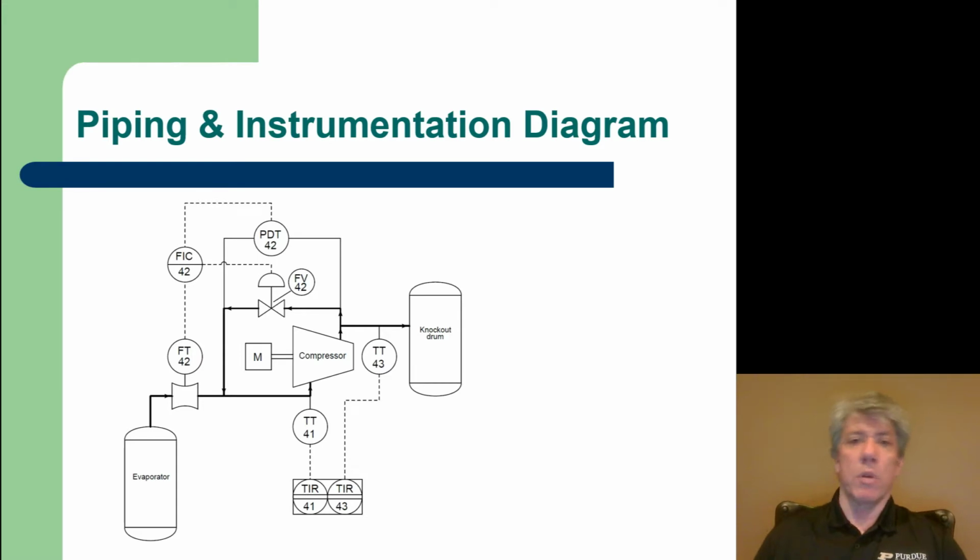So maybe it's a strip chart recorder. Modern electronic strip chart recorders have multiple lines they can draw at the same time. Even older strip chart recorders had that ability. So this is probably two separate lines on one piece of graph paper or one screen over time, so that you can see how the temperature across the compressor has changed with time. Because really, often it's the difference between those two temperatures that is particularly interesting.